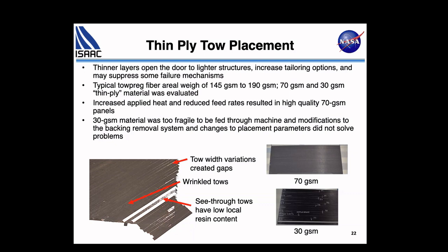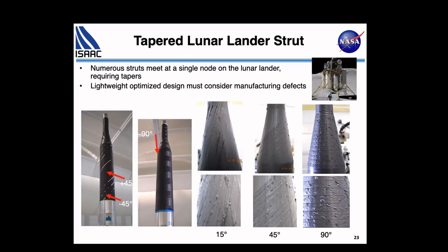It will be very weak. It will break. So you always put some fibers in multiple directions, but if you only need a very small amount, maybe you only put in a layer that's half as thick in the 90-degree direction as in the 0-degree direction. Particularly useful for spacecraft, where they are so very sensitive to weight.